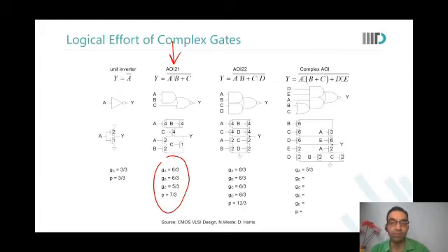What are you doing? We are essentially adding the NMOS and PMOS of the gate and dividing it by 3, which is the load of the inverter. And how are you able to see the way the sizing has been done? The equivalent resistance. Equivalent to the resistance of the inverter. Okay. So we've ensured that the equivalent resistance is the same as that of the inverter, come whatever be the case.